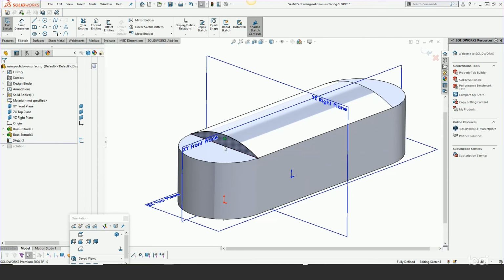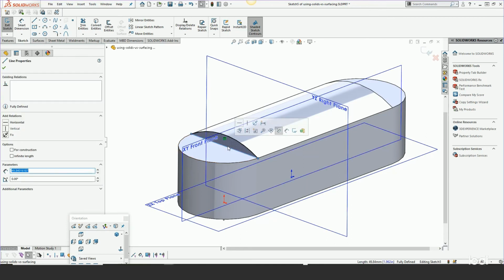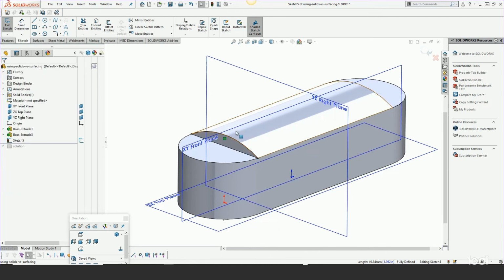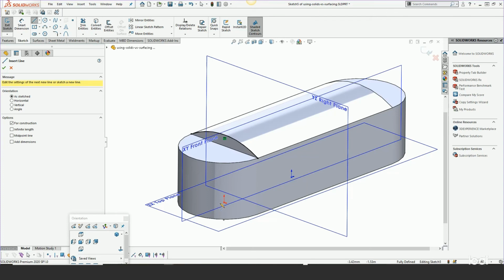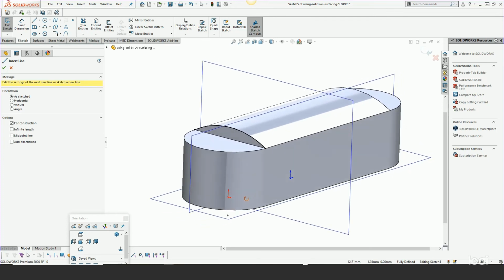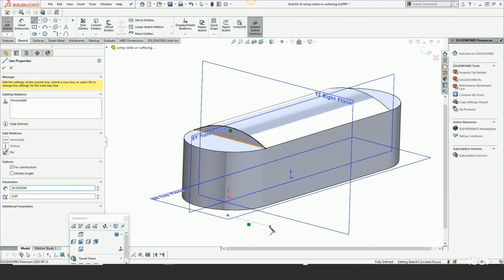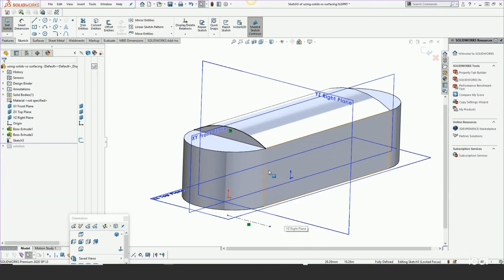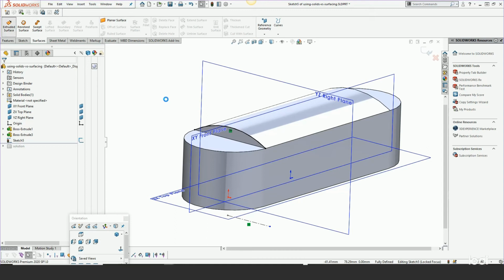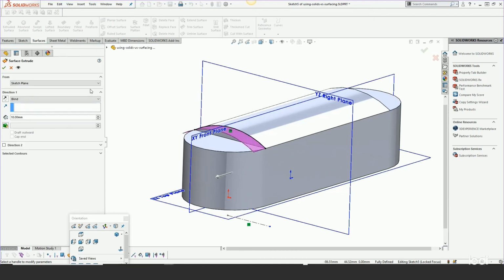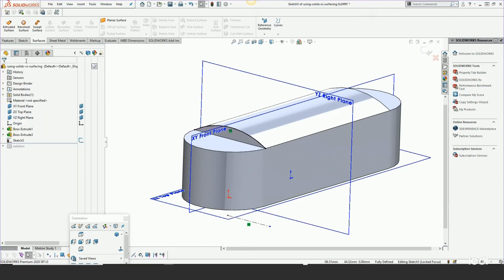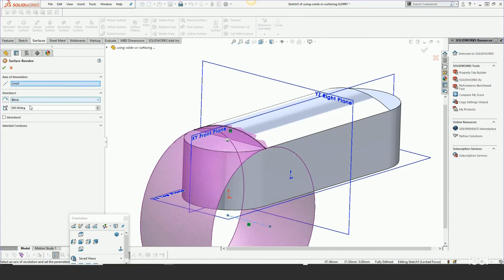Let's just delete this sketch element. And then simply, because we have a center point here, we're going to draw a construction line. And then we're just going to simply revolve that. I said revolve, Mark, not extrude. And just give it something like 15 degrees.